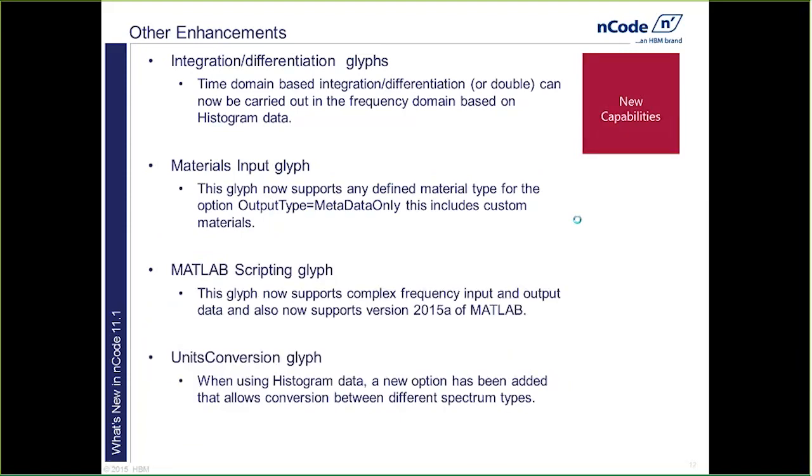Some other enhancements, quite a lot of these in the vibration area again. In terms of integration and differentiation, they've always been done in the time domain. But now that can be carried out directly in the frequency domain, based upon the frequency results in histogram data format. So you can differentiate or double differentiate, and the same with integration, directly in the frequency domain within either of those glyphs.